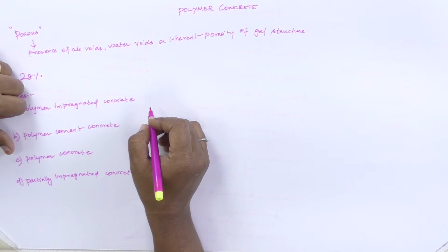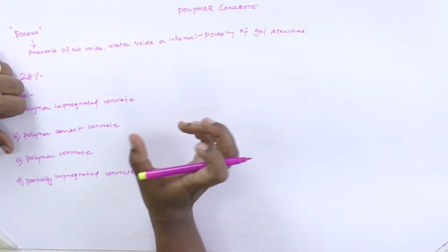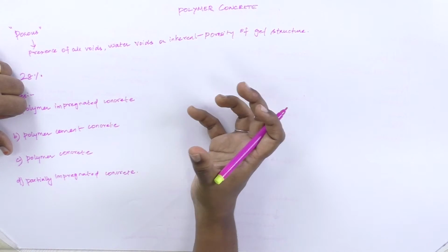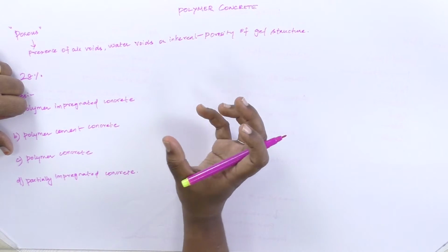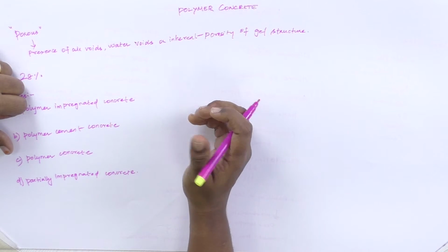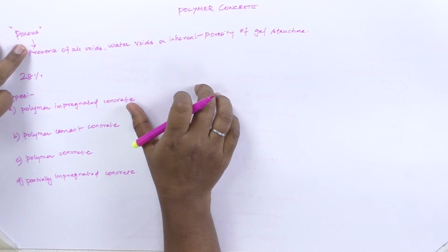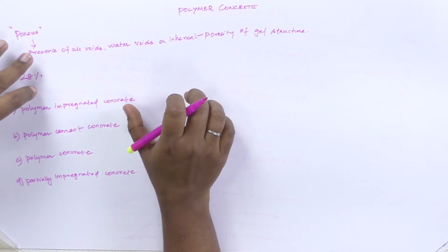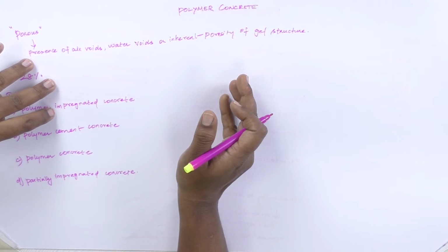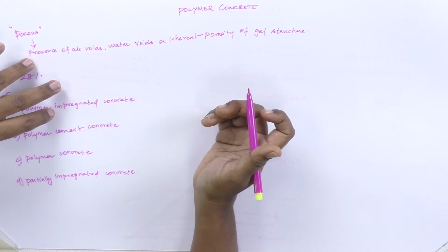Here, first the precast conventional concrete is dried in an oven or by dielectrical heating, through which the air voids are removed by vacuum. Then low viscosity monomer is diffused through the precast members, and subsequent polymerization is done either by a radiation method or by heating.